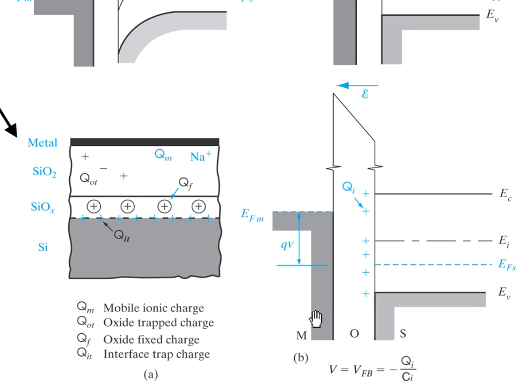Now you've seen the clean room, you've seen how we do wet etching, dry etching processes, and photolithography, and there are a lot of steps where the semiconductor has to be rinsed with water. One of the challenges in early semiconductor fabrication is that if you use impure water, water has ions in it, right? Positive and negative ions. Those ions can actually find their way into the oxide of the semiconductor. Let's say you're depositing your oxide layer, and then you decide to clean the wafer in water.